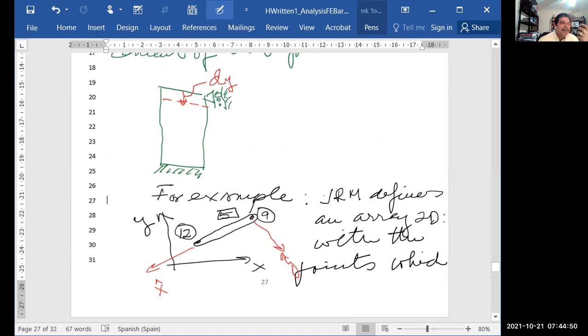And the result of that is that we know that value and we're going to calculate the force that we need to apply on this end in order to get that displacement. Okay, so if you have a support which doesn't move, of course, the value is going to be 0. And of course, the force that you need to specify there is going to be the reaction.